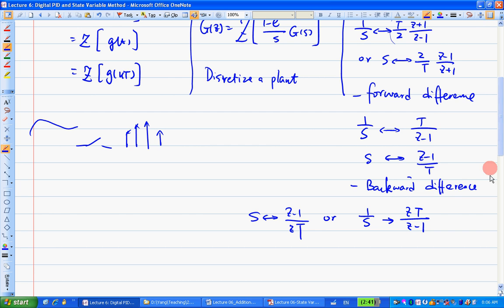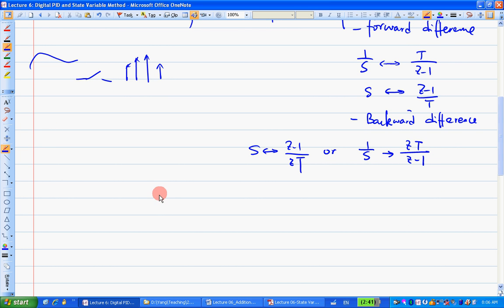What you can do is try to use Simulink. You have a signal generator, so let's say you generate a certain kind of sinusoidal signal. Then you create this 1 over s block, that's an integrator.